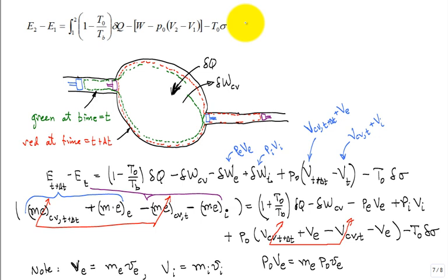So we said we're going to start with this equation that applies to a closed system that's going to deform. So what you do is you have a control volume that looks like this round thing right here, but you have an inlet pipe and an outlet pipe. See how I've shown it? And you have to pick a pack of fluid that completely fills the control volume plus is about ready to flow into the control volume over the next time step delta t.